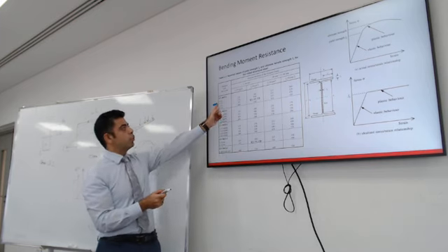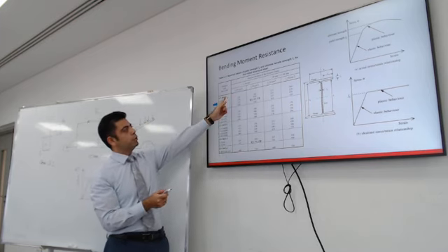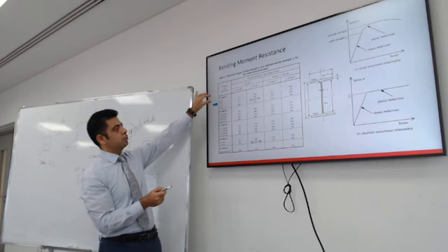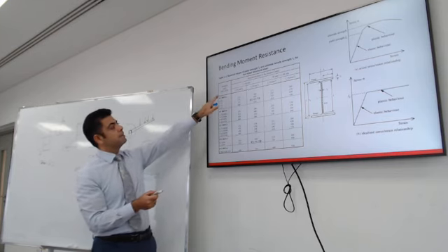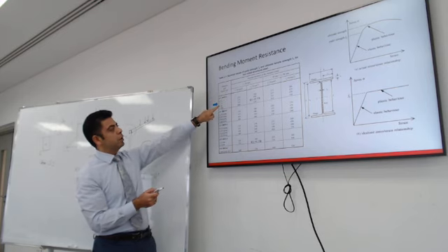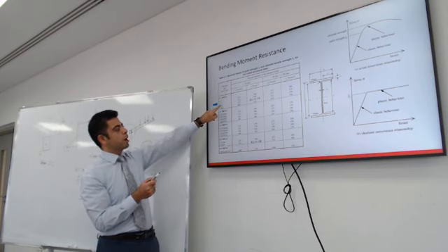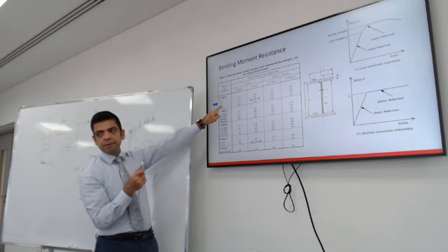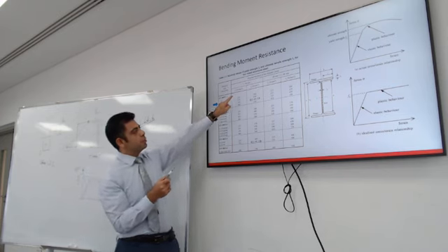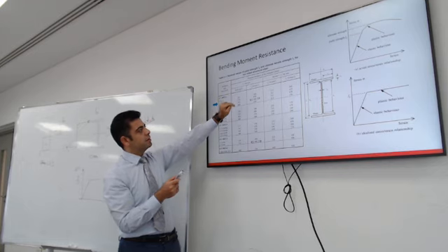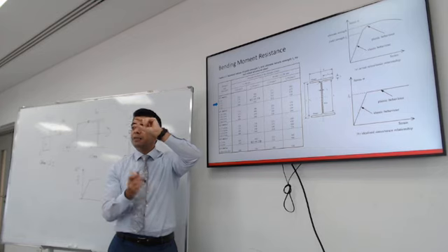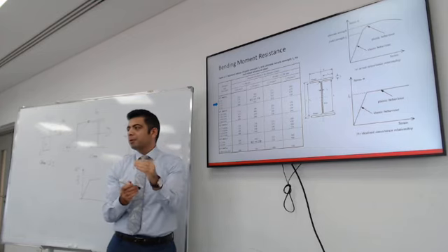So according to the European standard, there are special tests and special requirements to fulfill these steel grades. Let's say we're going to choose, this is one of the most common ones, steel S275. The 275 represents the yield stress if the thickness of the section you choose is less than 40 millimeters.